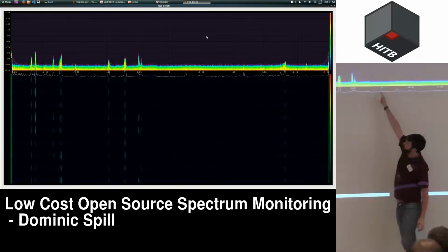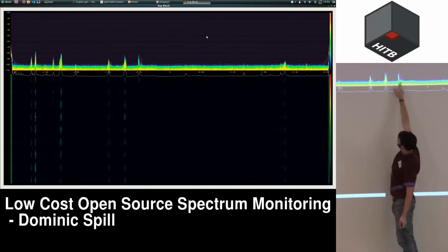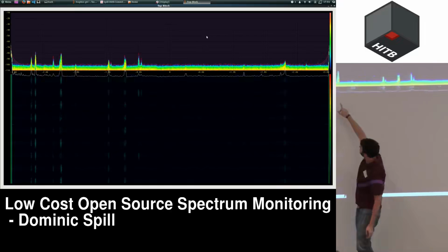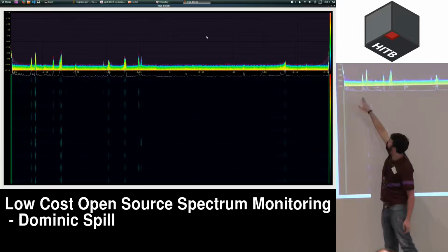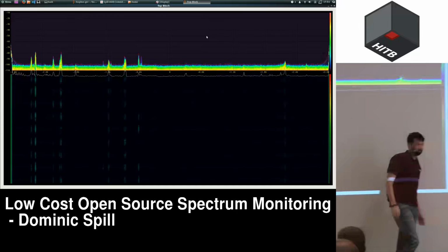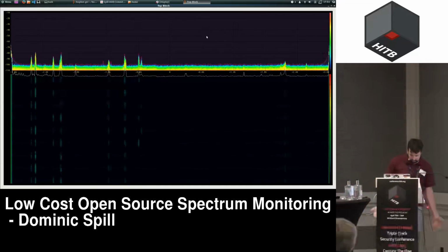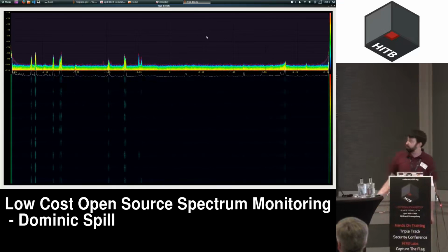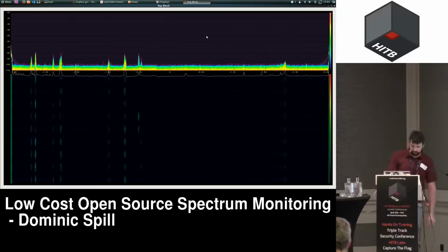We've got the 0 point in the middle. So negative 0.6, that's the 2.4 gigahertz spectrum, and various other things. Down here, we're pretty close to DC, so we get a bit of distortion. And I'm not sure what's at negative 2.4. Any suggestions from the front row? What's down at, what is that, negative, that's about 900 megahertz, I guess. So that's probably where that spike is. I have no idea what around me is transmitting 900 megahertz, potentially the microphone.